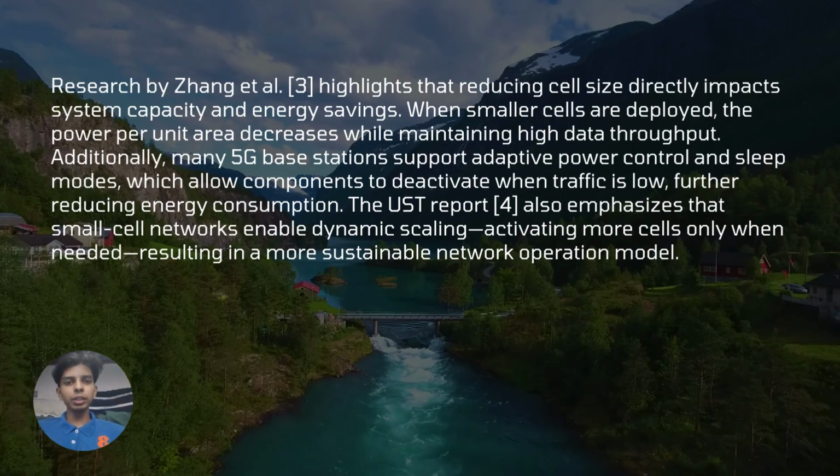Research by Zhang, which is the third journal, highlights that reducing cell size directly impacts system capacity and energy savings. When smaller cells are deployed, the power per unit area decreases while maintaining high data throughput. Additionally, many 5G base stations support adaptive power control and sleep modes, which allow components to deactivate when traffic is low, further reducing energy consumption. The UST report, which is the fourth journal, also emphasizes that small cell networks enable dynamic scaling, activating more cells only when needed, resulting in a more sustainable network operating model.